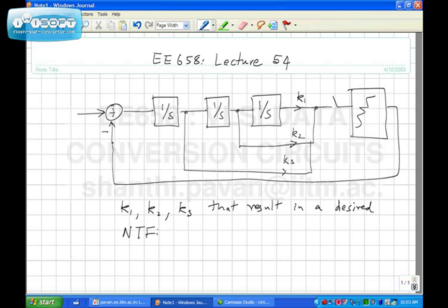Once this is done, the thing is to build a macro model either in Simulink or in MATLAB and simulate the differential equations, right? So please note this is like a mixed system. It's continuous time in some part and discrete time in other parts. Okay, so to that extent, the simulation will take a long time, especially when you put transistor level models for the loop filter as well as the quantizer.